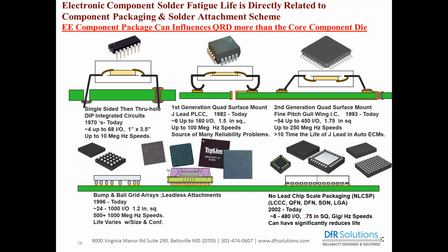When we went to the more complex double-sided plated through-hole circuit boards, our reliability, our durability just skyrocketed. And nobody could understand this, because the reliability experts at the time were using the now widely discredited Mil Handbook 217 reliability prediction by part counting and tabulation of the generic failure rates of generic components.